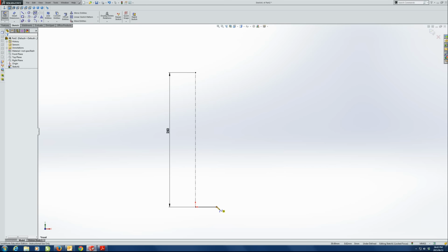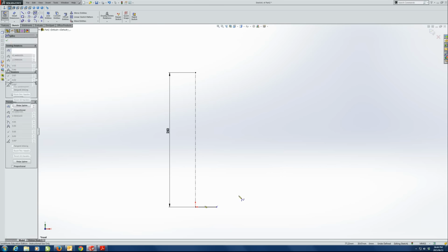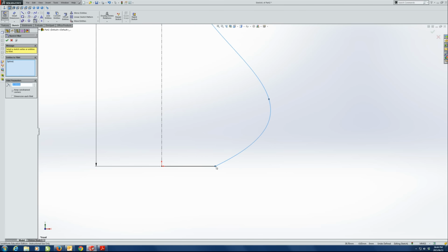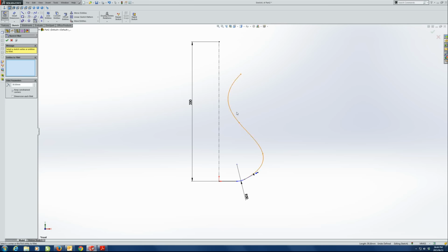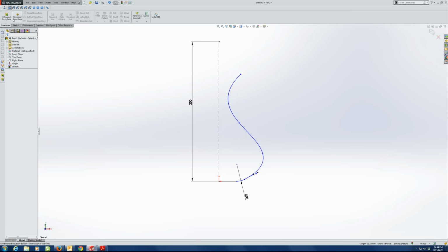And the spline tool allows us to make a bit of a smoother looking surface on our vase, right? And you can see this makes for some pretty nice curves. Okay, and obviously we double click again once we're done with our spline. Okay, I'm going to fillet the bottom edge, just this corner. Let's make that a bit bigger. Okay, basically we're now going to leave the vase just like this, and we're going to do a revolve.